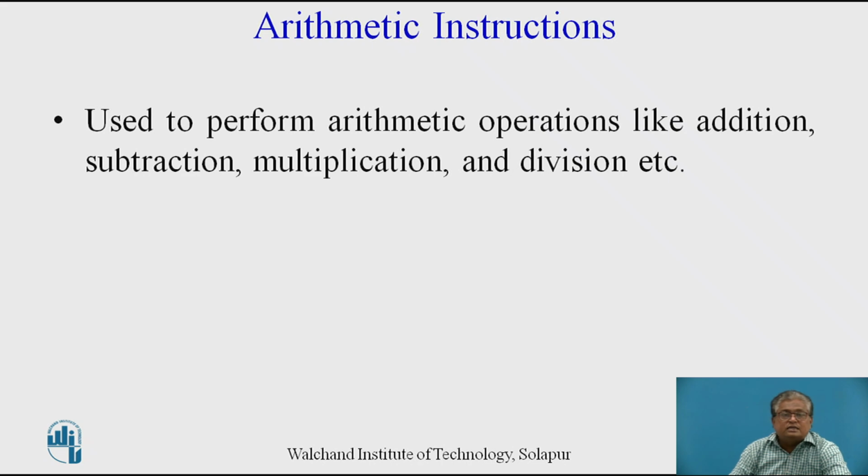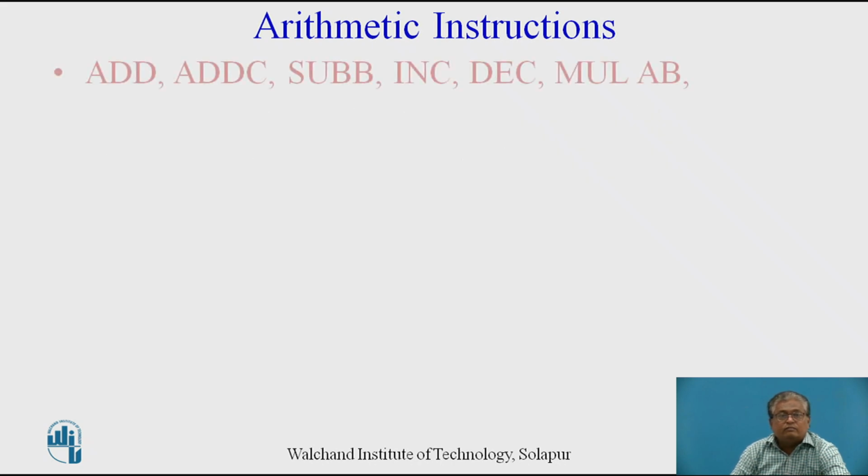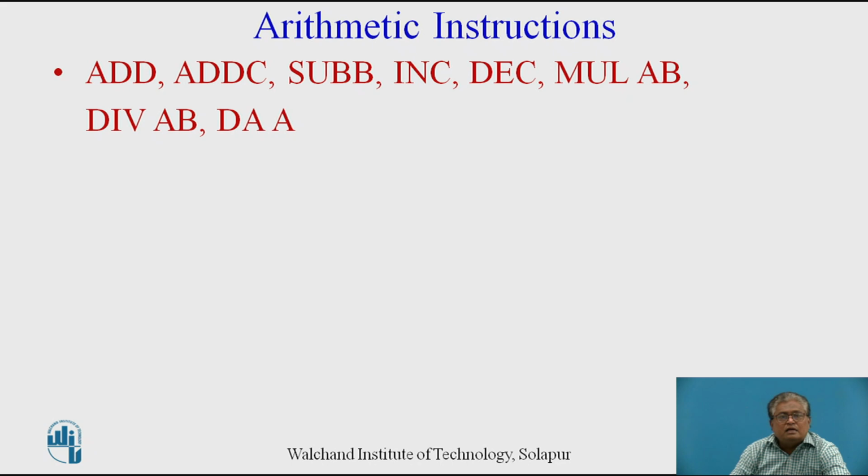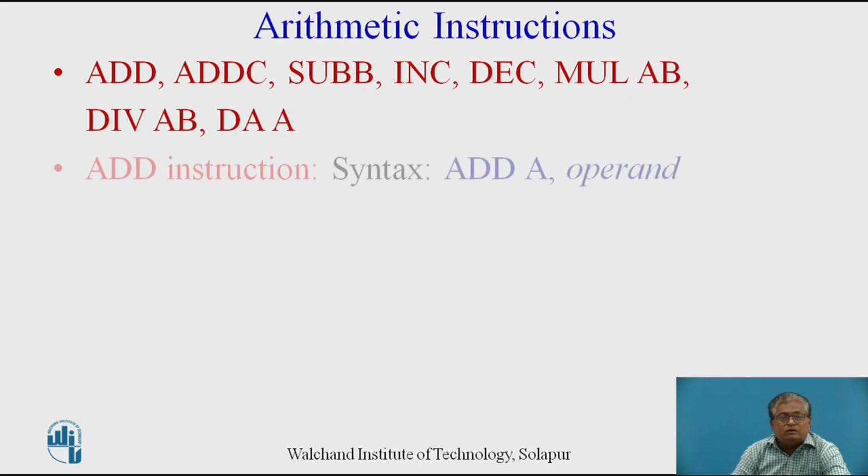So arithmetic instructions are used to perform the various arithmetic operations like addition, subtraction, multiplication and division. So ADD, ADDC, SUBB, INC, DEC, MUL AB, DIV AB, DA. These are the various arithmetic instructions defined for the 8051 microcontroller.